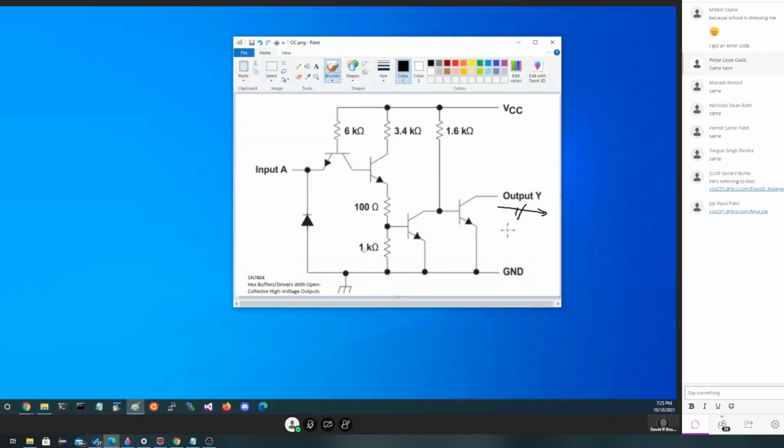So unlike the one we saw in the last illustration, the TTL inverter, this TTL compatible device here allows us to sink current into the chip when we have this transistor turned on. And since this is a buffer circuit, if there's a 0 here, we get a 0 there. But when it's high, nothing comes out.